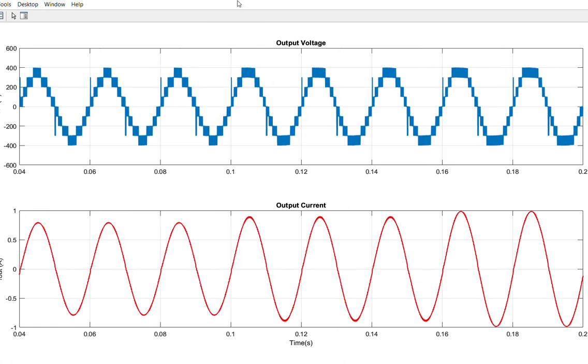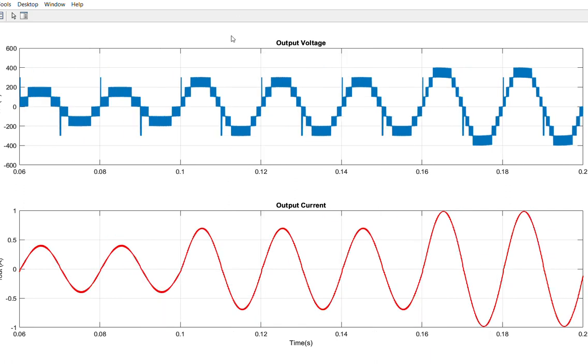And this is for the inverter voltage and current analyzed for different modulation indexes equal to 0.8, 0.9 and 1. At this condition, the inverter's voltage levels are maintained. And this is for load voltage and current for another condition of modulation index 0.4, 0.7 and 1. The inverter's voltage levels are changed to 5, 7 and 9 levels for modulation indexes 0.4, 0.7 and 1 respectively. Consequently, the load current value is changed.